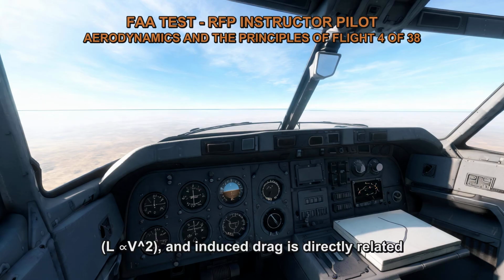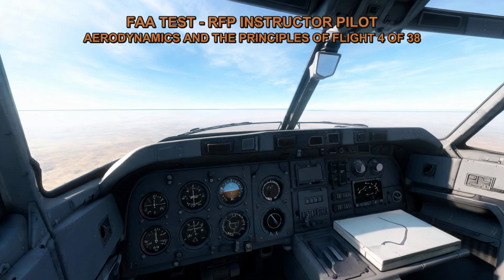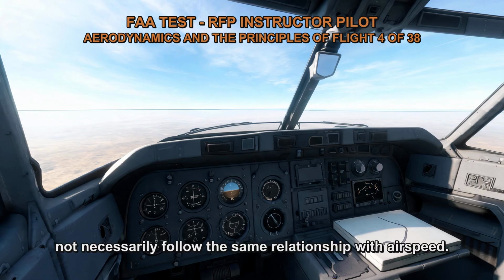L is proportional to v squared, and induced drag is directly related to the lift generated by the wing. Therefore, induced drag varies inversely with the square of the airspeed. It's important to note that this relationship holds true only for induced drag. Other components of drag, such as parasite drag, which includes form drag and profile drag, do not necessarily follow the same relationship with airspeed.